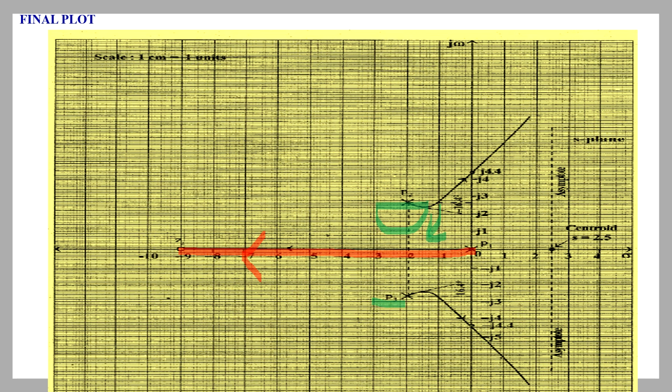Then take your protractor and mark it on P3. Face the protractor upwards as we need to mark the angle +16.4. So plus 16.4 means anti-clockwise, -16.4 means clockwise. And you just mark +16.4 and -16.4 simply as dotted lines. No need to mark anything else. Just mark the angles there, right? Then let us draw the final branch.